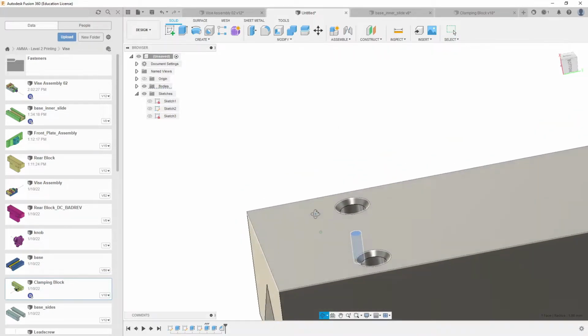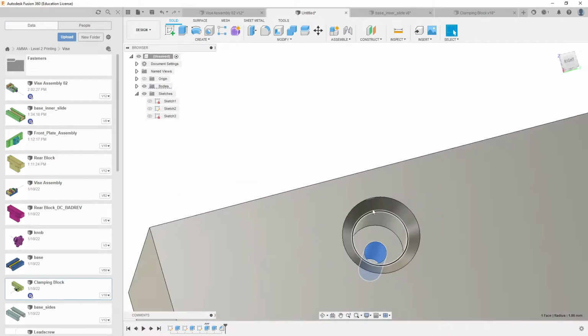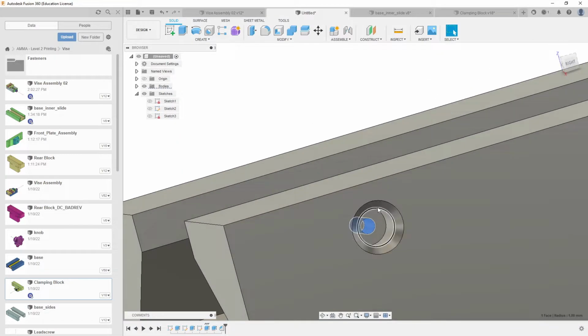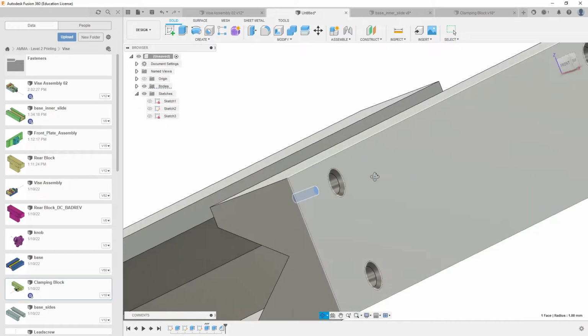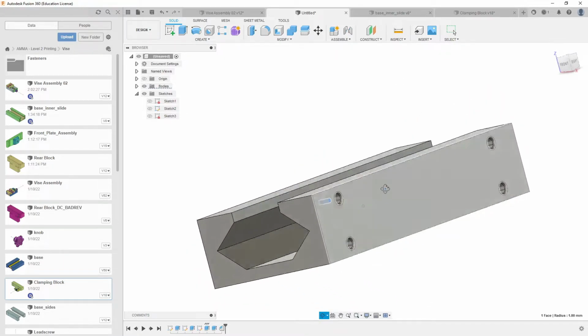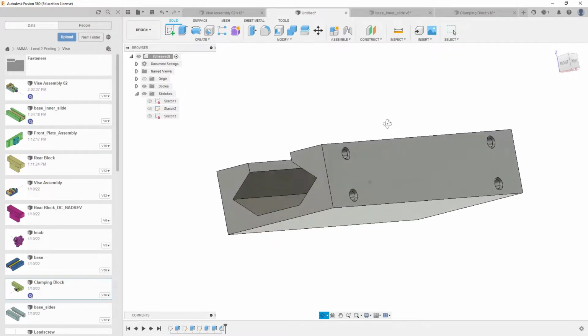Now the chamfer is to help with the excess plastic that melts out to give it somewhere to go. So as you stuff the insert in here, the plastic around here is going to start to melt into the little grooves and such in the insert, but some of it invariably is going to come up and out, and that's what the chamfer is for. Okay. I feel it also helps us kind of align the thing a little bit better as well. Probably a little bit of imagination, maybe not, right? But we have it. So hopefully this works out okay, and I just didn't screw us up royally because we had a pattern and I just deviated from it, but we'll see how it goes.